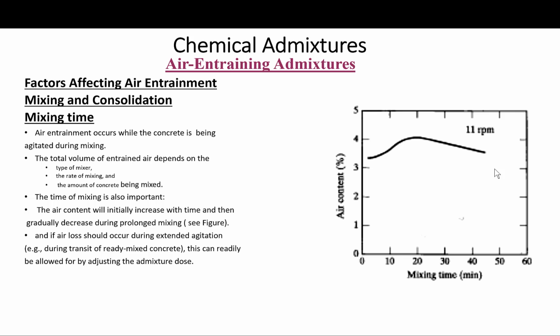I mean, there are the transit mixers, from the time they leave the mixing plant until they arrive at the job site. This time may be increased. So basically, I go back to my key point, trial batches, trial mixing. In case you have extended mixing time, you may have to adjust the dosage in order not to miss the optimum dosage required due to extended mixing.